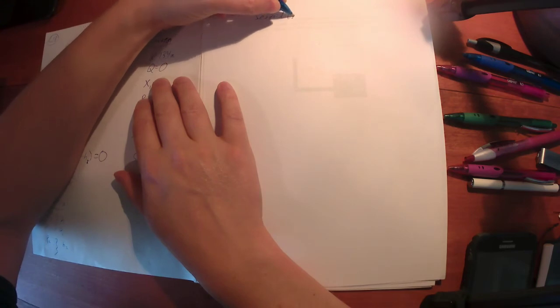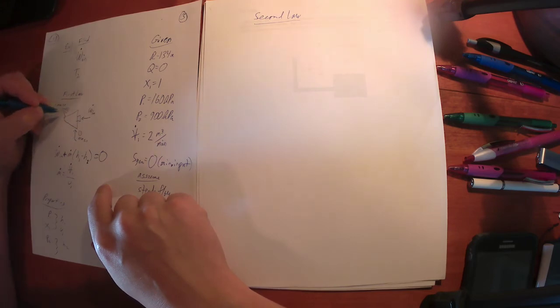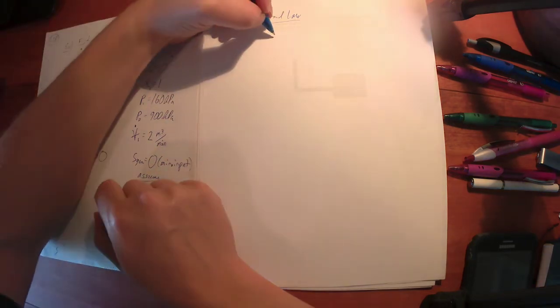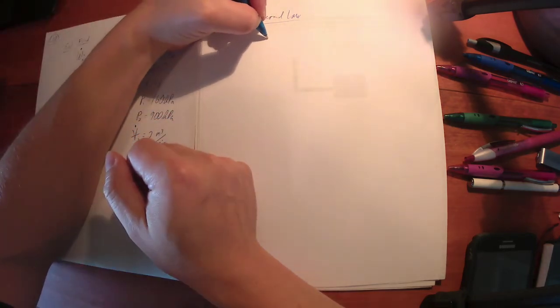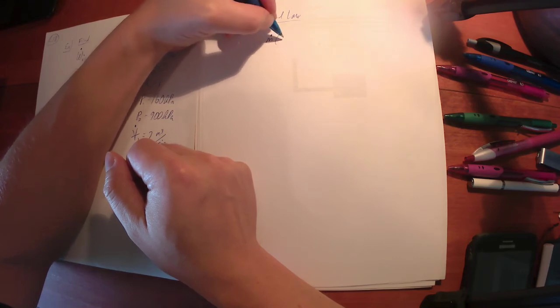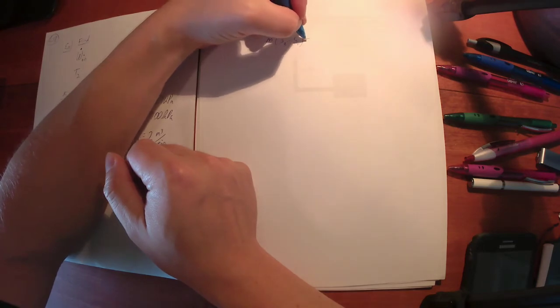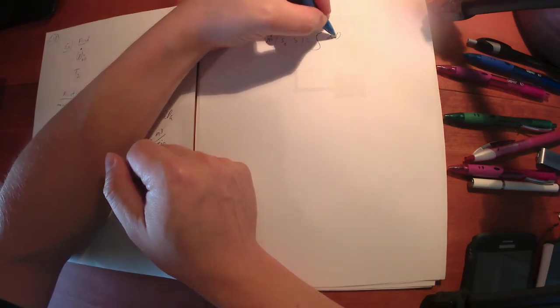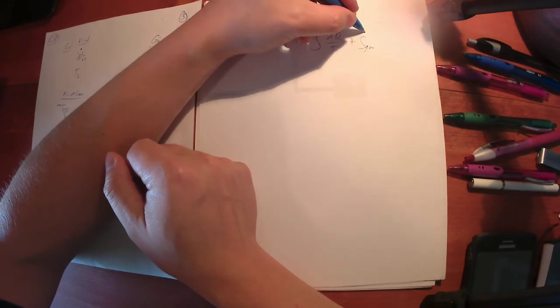So let's draw the second law for this thing. What is the second law? Is this a process from state 1 to state 2? Sure. I've got an inlet we're calling 1 and an exit we're calling 2. Which one do we use? Well, we could use any of them, I think. It is a control volume, so if you wanted to say m dot times little s2 minus little s1 is equal to the integral of del q dot over T plus big S gen dot, that's okay.